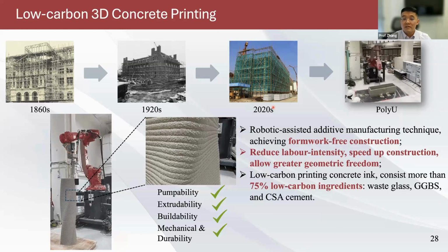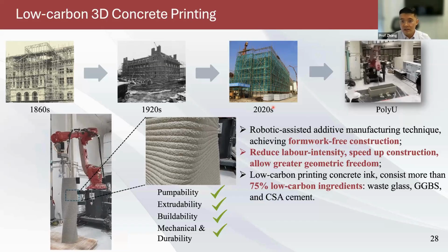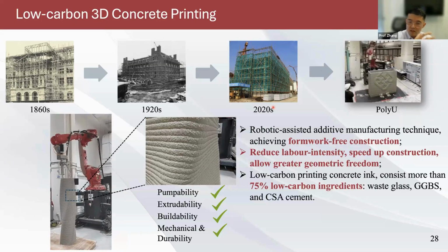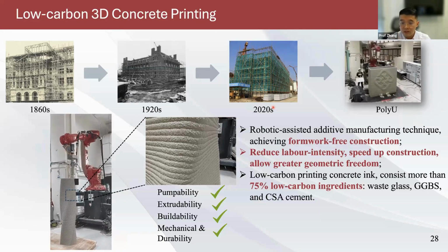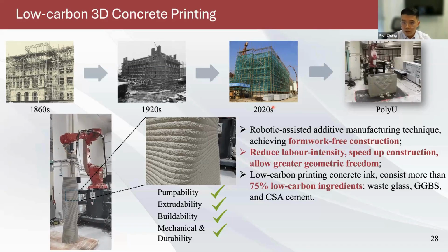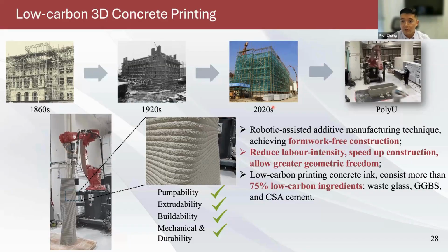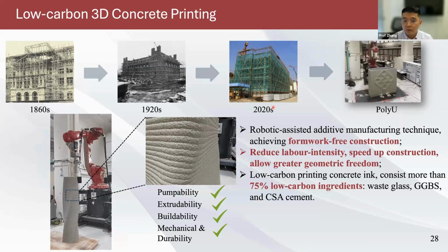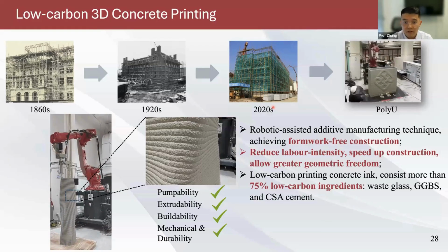Also, formwork is the number one solid waste source for on-site construction, because wood formwork cannot be reused after a couple of uses. It is also costly, particularly for curved or special dimensions, where the cost is very high.